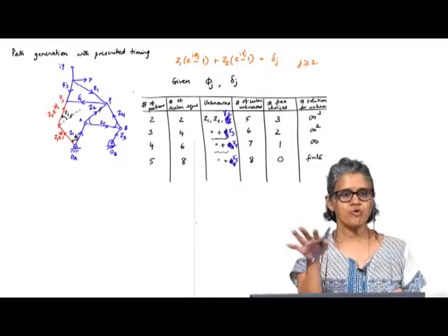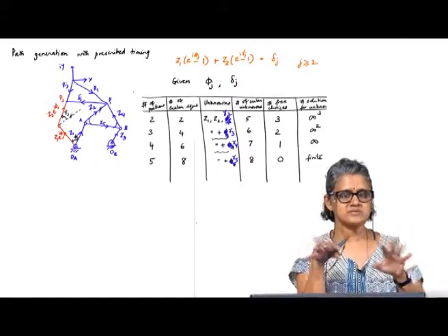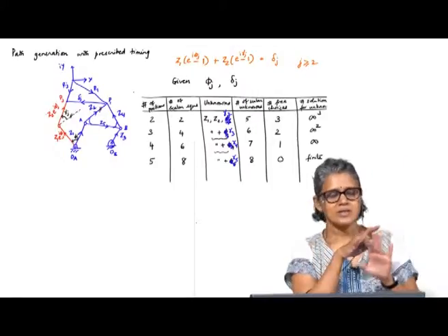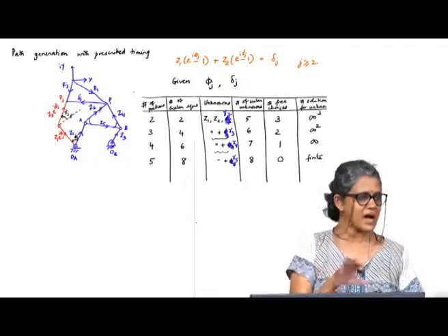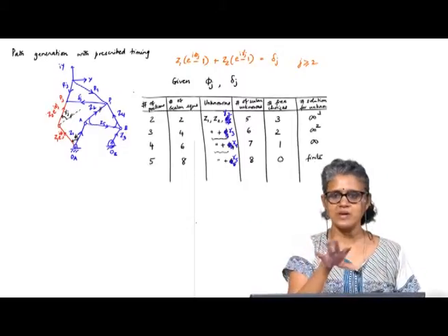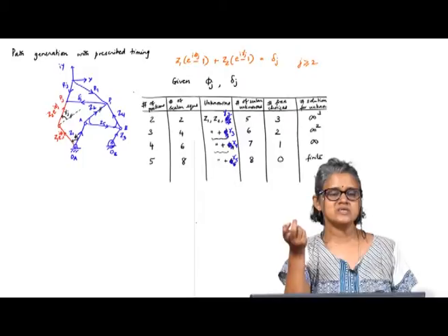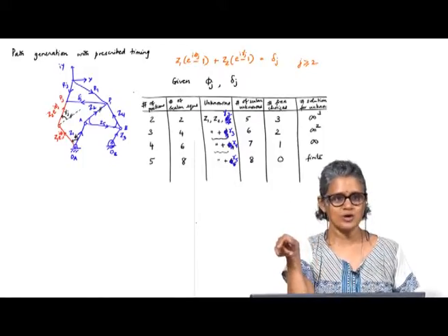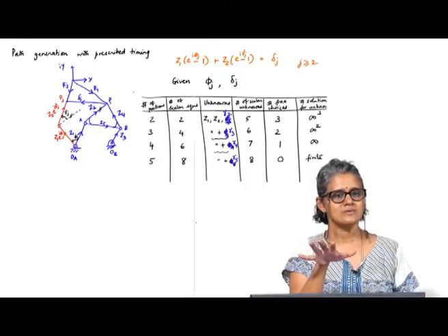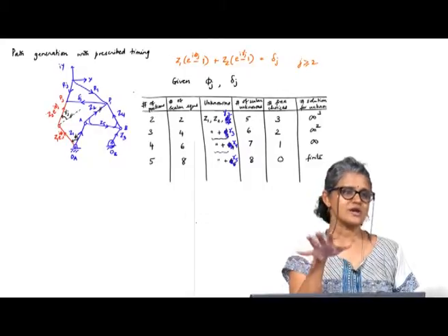See, every 4 bar has all these relationships. There is going to be a coupler point. The classification is based on your requirement. Ultimately, you are getting a 4 bar. In the 4 bar, if you decide that the input output angle relationship is what you want, then you call it a function generator.